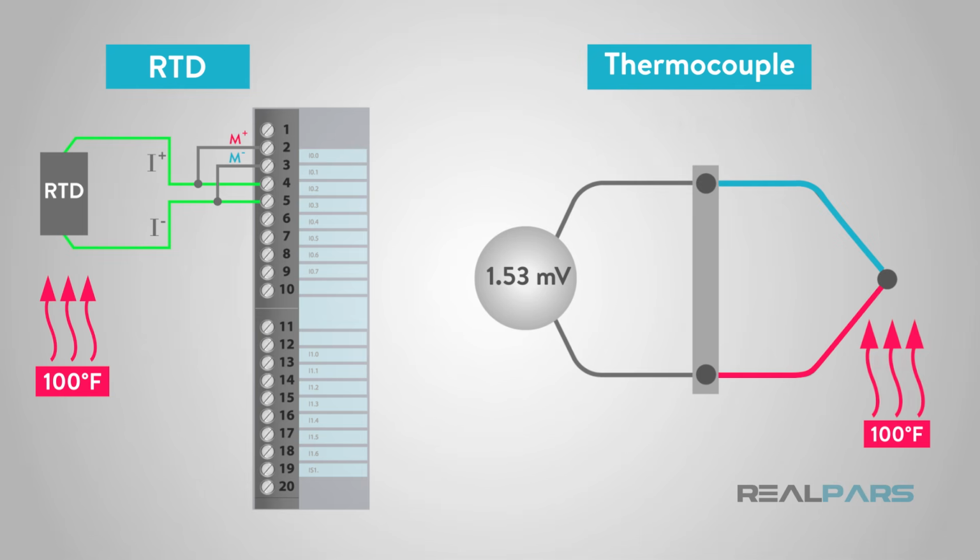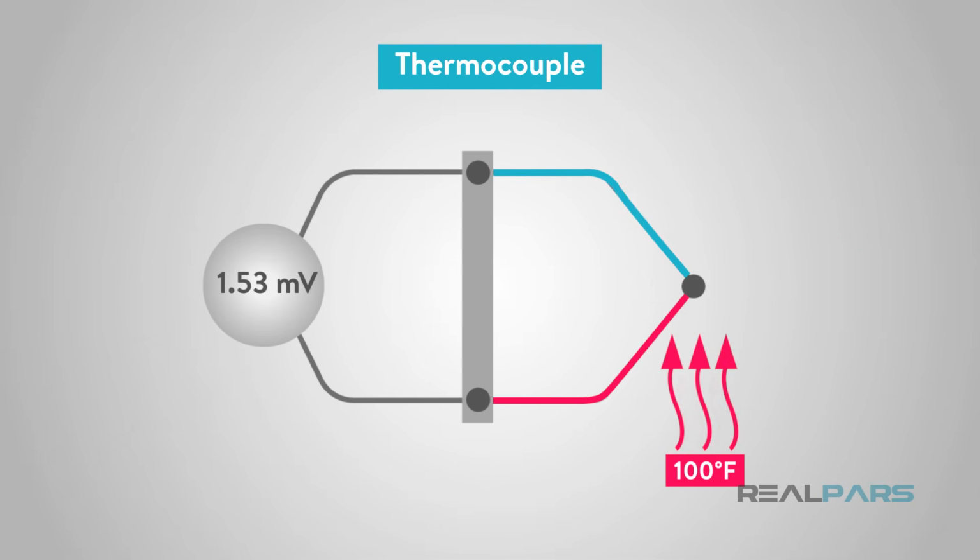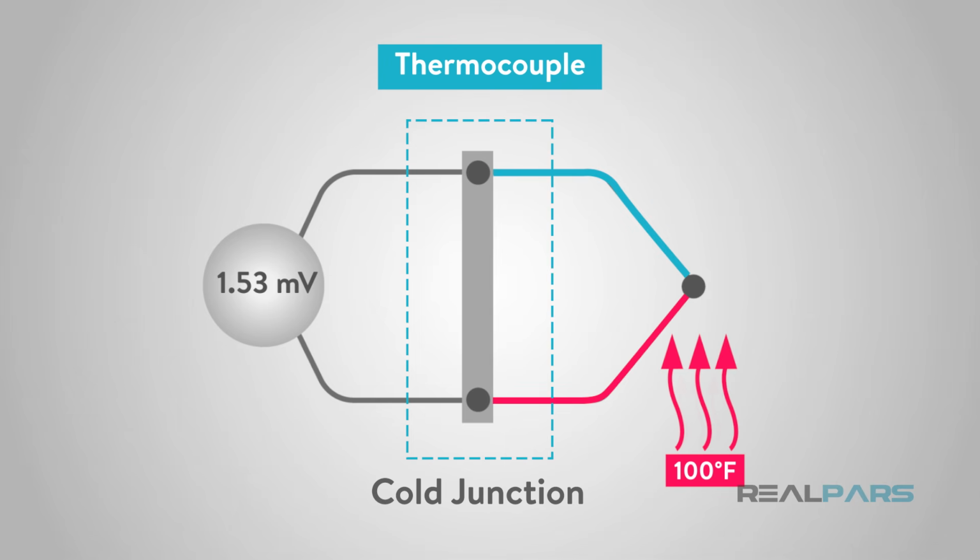The main restriction of thermocouples is the accuracy, which doesn't make it the best solution for precise applications. Also, thermocouples need a reference measurement point called the cold junction. The thermocouple junction is often exposed to extreme environments, while the cold junction is often mounted near the instrument location.